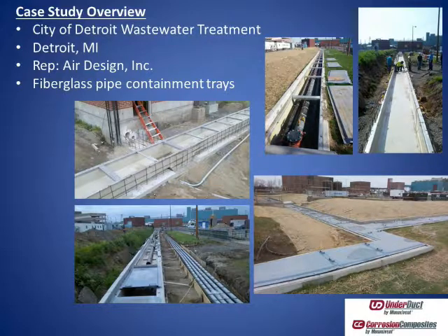We have 316 stainless steel angles on the top edge, all fabricated here at Crawford. We have channels and angles crossing over every 4 foot. These support the covers. They're concrete encased, and then the covers are all fiberglass, and they're all end-to-end matched.